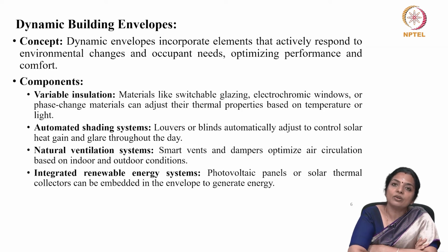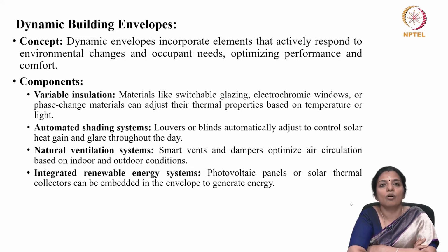This can happen throughout the day. On a particular day, from morning to evening, the position of the louvers or vertical fins or blinds will keep changing to ensure that you have indoor conditions as per the occupant's desire in terms of either solar radiation or daylighting.